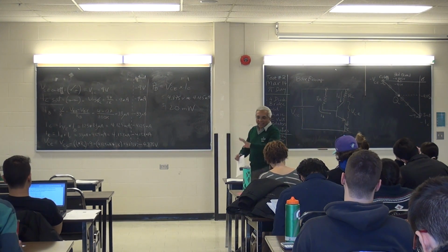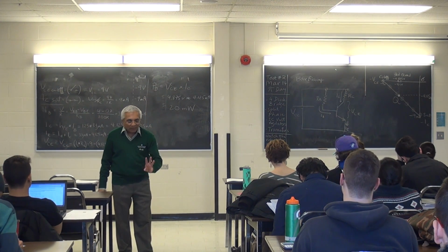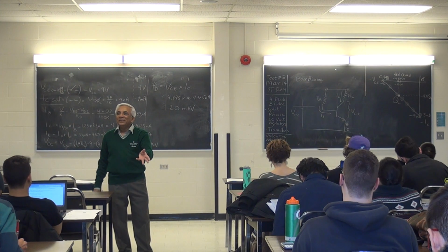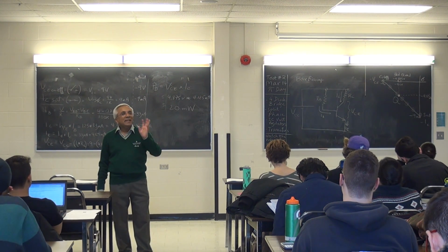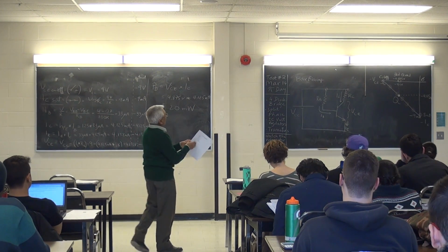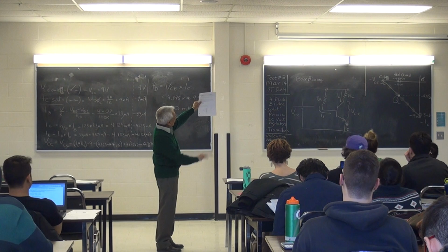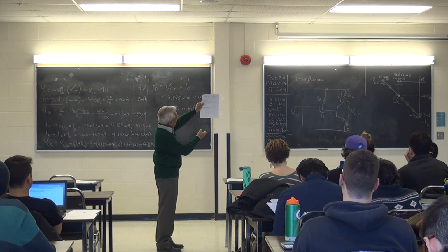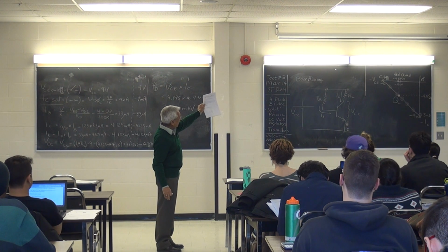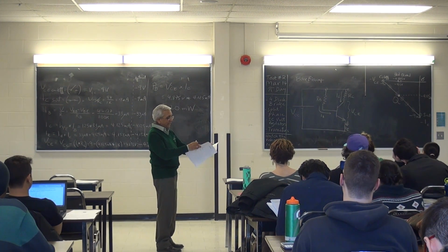So it's everything the same as what we did earlier, but everywhere that I used a VBB, I now use what? VCC. Because VBB and VCC are one and the same in this circuit. Okay? So this is the same circuit that you see on page 1. It's drawn a little different, but it's the same circuit. IB, IC, VCE, and one source voltage called VCC.